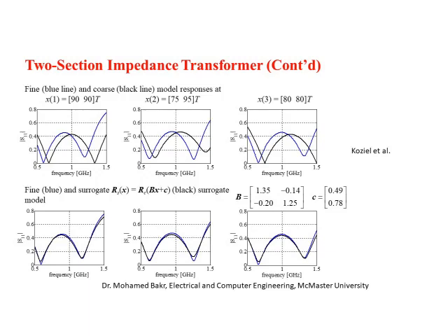However, if we take the vector parameters x, which is L1 and L2, multiply them by this matrix B, and add to it this vector C, and then after you get these new mapped parameters, you call the coarse model simulator with them, you will see that the fine model and the coarse model are identical. Okay, so I could use this mapped coarse model, and this is called the input mapping because I map the input parameters. I can use it to replace the fine model, which could be more accurate or more time intensive depending on the case.